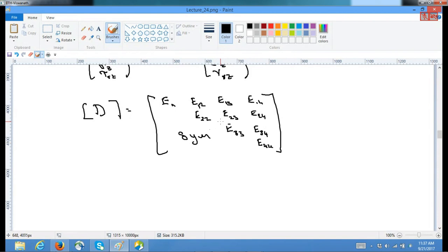Further, all these coefficients will vary depending upon the material symmetries. The material with full symmetry is isotropic, with further less symmetry is orthotropic, or generally anisotropic. So depending upon whatever this is, these coefficients would change. However, in this class we will restrict ourselves to an isotropic case. In the case of isotropy, we can represent our D matrix simply by this relationship. So the D matrix for the axisymmetric and isotropic material is represented by the following.